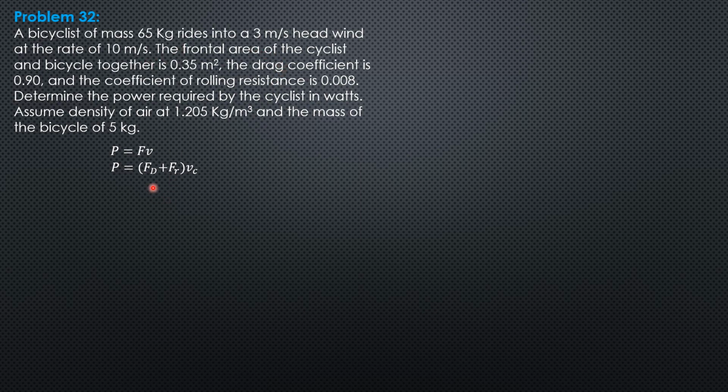However, the drag force is a function of the relative velocity of wind and the bicyclist, because the bicyclist is riding the bicycle into a 3 meter per second headwind. So the relative velocity would be 10 plus 3 or 13 meters per second.